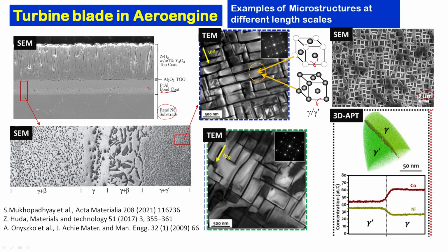So this is a picture from 3-dimensional atom probe tomography. This is a tomographic technique. You can clearly see between 2 gamma prime grains there is a boundary which has a lot of segregation of elements, right, and this is segregation of nickel actually, you can clearly see. So one can actually even look at the distribution of elements, which one is stabilizing the gamma prime phase and many other things. So we can also discuss what will happen in the bond coat, reaction layer.